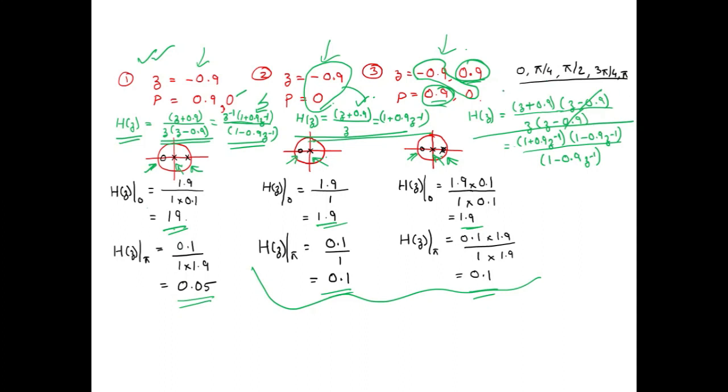But please do not do that. Why? Because if you do that, then you are eliminating one zero and one pole from the mathematical expression itself. So when you calculate the positioning of the poles and the zeros, you will be missing one pole and one zero. That would make your result incorrect.